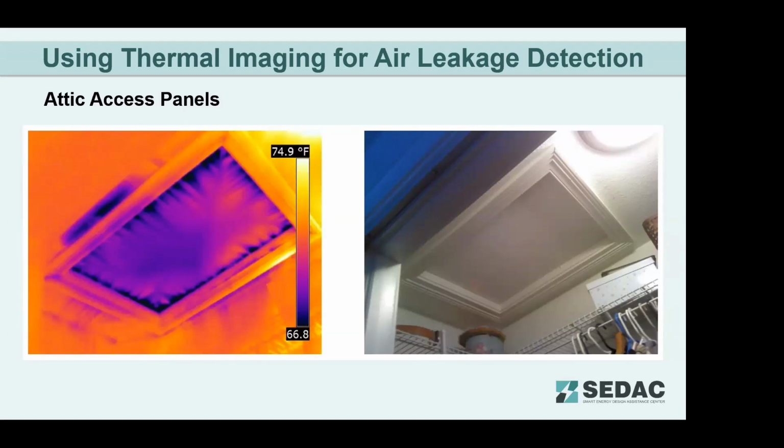This is a cold weather shot. So again, the darker colors are bad colors. Again, notice the streakiness here. That's, again, the blower door running, giving me that 20-mile-an-hour wind. The camera's on at the same time. So you can actually see it. So we're missing some weather stripping under this attic hatch, and even some caulking and possibly some missing insulation here on the side.